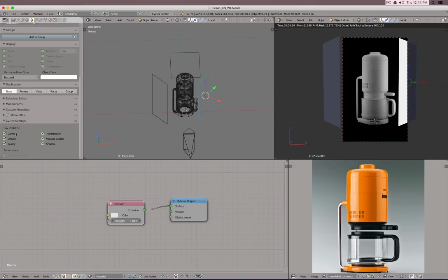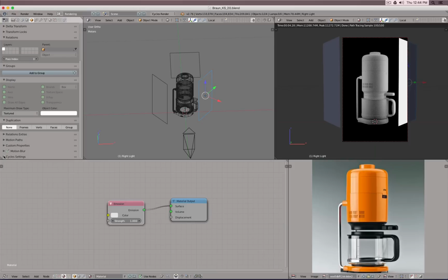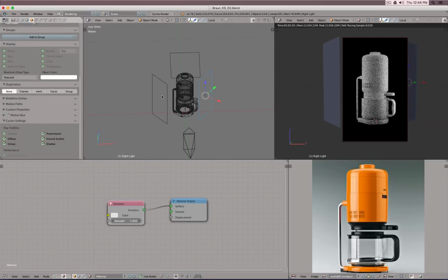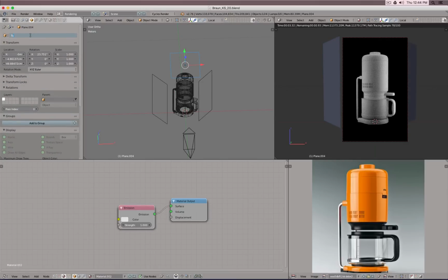And maybe this light actually I would like not to show up in my rendering. So you can click an object. You go to the object properties. This is, for example, right a light. And then we say turn the visibility for the camera off. Same here, same there. And that actually means that the light is still there. It emits light into the scene. However, it will not show up inside the camera.